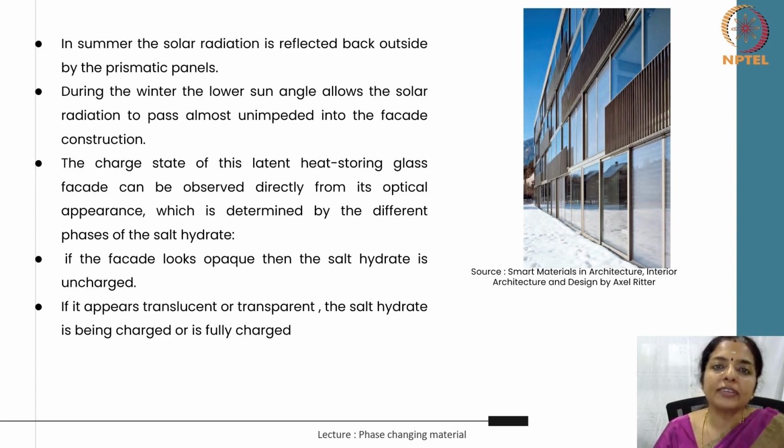If the facade looks opaque, as seen from outside through the prismatic panels or from the inside, then the salt hydrate is uncharged. If it appears translucent as seen from outside through the prismatic panels, or transparent from the inside with no printed pattern, the salt hydrate is assumed to be charged or fully charged. In summer, the solar radiation is reflected back outside by the prismatic panels.